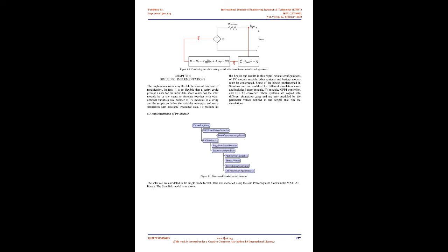B: Standalone systems. PV systems not connected to the electric utility grid are known as off-grid PV systems, also called standalone systems. Direct systems use the PV power immediately as it is produced, while battery storage systems can store energy to be used at a later time, either at night or during cloudy weather. These systems are used in isolation from electricity grids, and may be used to power radio repeater stations, telephone booths, and street lighting. PV systems also provide invaluable and affordable electricity in developing countries like India, where conventional electricity grids are unreliable or non-existent. Figure 2.12: Standalone PV system.